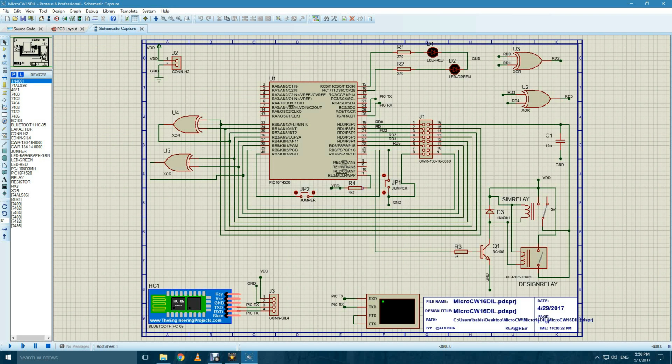Now, it was suggested that we try to extend the design to support DIL 16 family products, and that was actually a very simple process. We replaced the socket with a 16-pin socket, but that comes with an inherent difference. Before, pin 7 would be connected to the ground, like it's shown here when we are testing DIL 14 devices, but